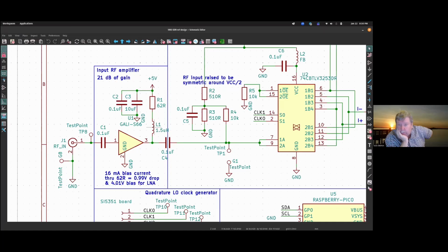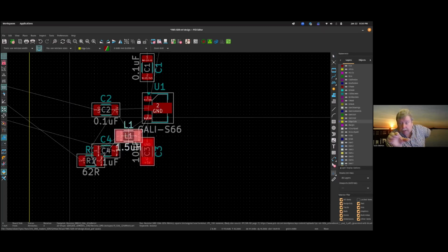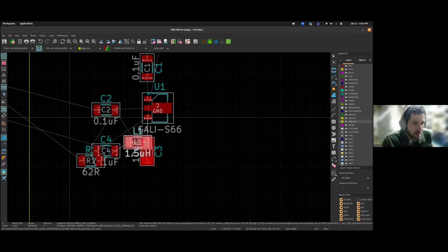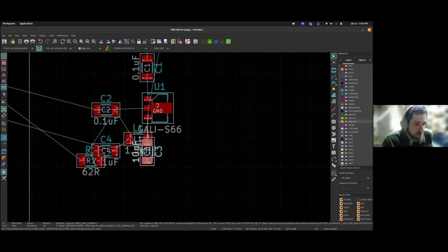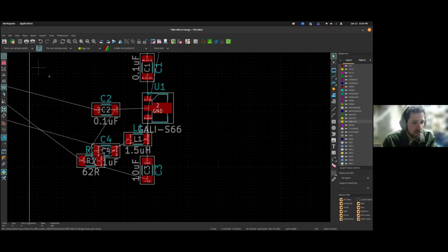I might add as well, if you do have a trace length, that it has to be fairly precise, because it's a 50 ohm trace, and that's dependent on your substrate thickness as well as the... Yes, that is something we will get to in a little bit when we get to actually routing the traces. Is how wide do you need those lines to be? And yes, we will get to that when we're done with placement.